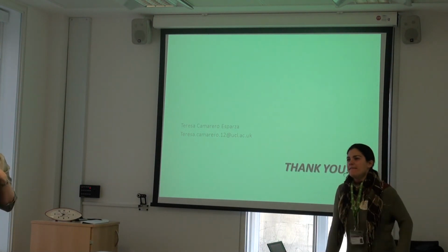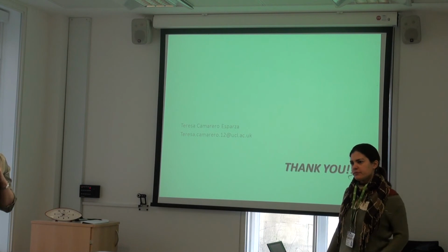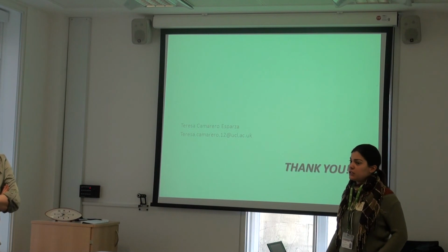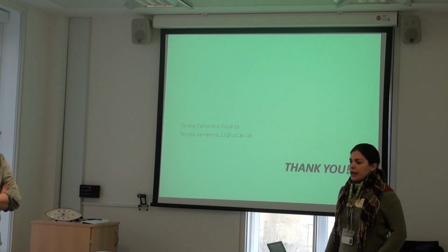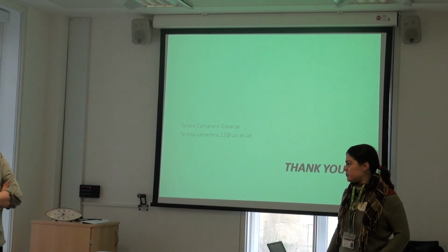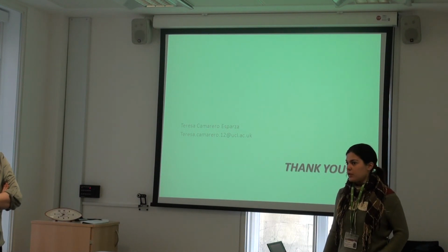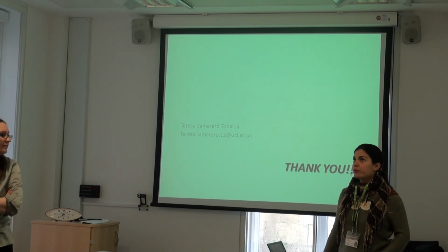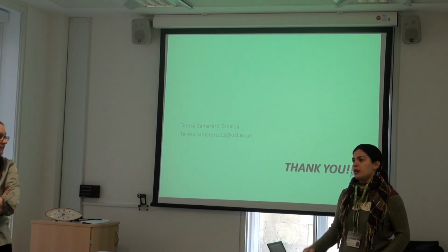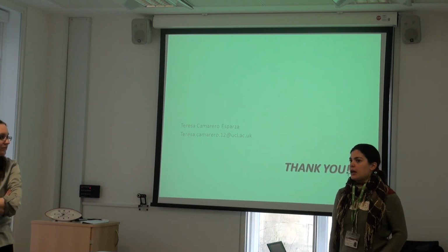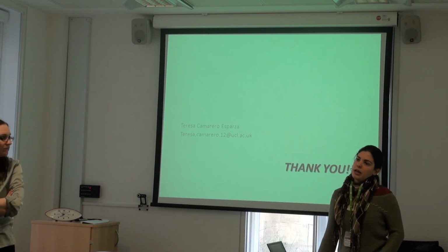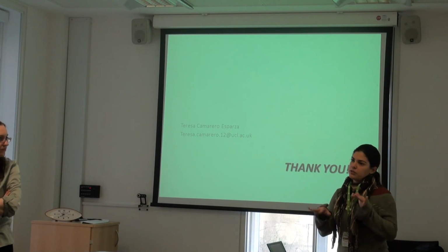Teresa, just earlier on you were talking about improving the carbon content, so you want to increase that carbon going in. Okay. Yeah, just COD. And what do you suggest doing? Adding. The basic problem that both have is that the amount of easily biodegradable carbon is very low. So vegetable waste and meat waste, there are a lot of sugars there, and that would increase the amount of readily biodegradable carbon, and it would balance the situation more.